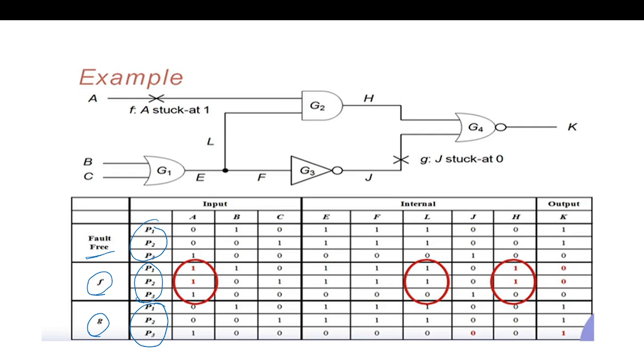And in the parallel pattern simulation, we have seen that we keep the patterns in parallel. If we have a W-bit word, W test patterns are packed and then simulated. So first the fault-free, then the faulty. For a single fault: first fault-free simulation, then for each fault, fault injection and then faulty circuit simulation. Here the advantage is that if a fault is detected, we can drop the fault, because we are simulating patterns in parallel. It is best for simulating test patterns that come later, when the fault dropping rate per pattern is lower. And this is not suitable for sequential circuits.